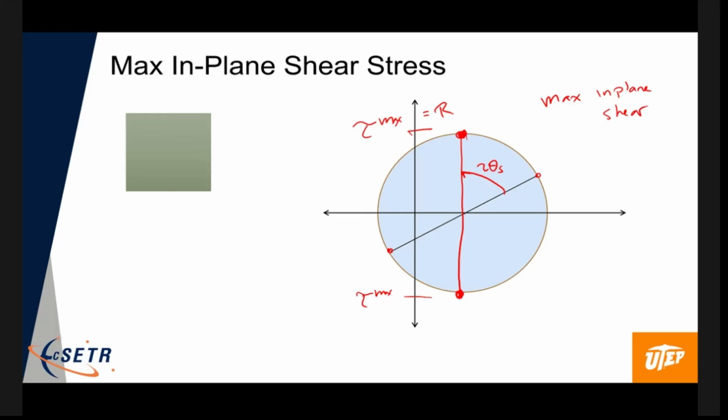And there is also, it's not like the principal stress. It's not like it's only shear because you have a normal stress value, which is the average, okay? So if we rotate that off a Mohr circle, right, this angle here is theta s, and we would get the normal stress, which is the same on all the faces, of that average stress, and then the shear stress is like the following.